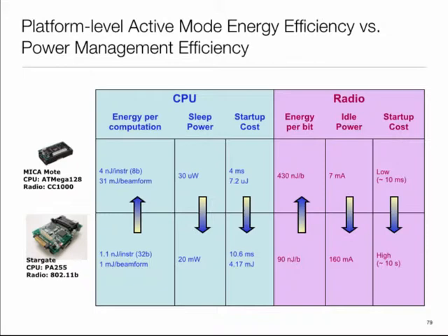Another good example would be a modern higher end processor. They do all sorts of tricks, like lots of cache, for example. They may have out of order execution of instructions: if an instruction which is out in the future can be executed because it doesn't have any data dependency, they will do that. They have multiple hardware units which may lie idle, but they're gaining speed.